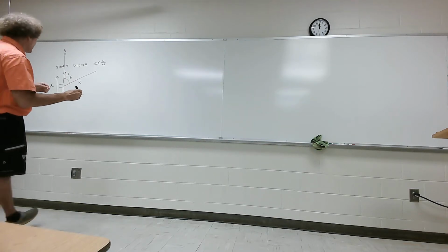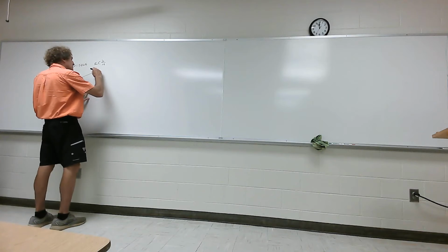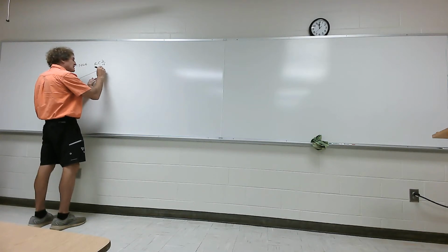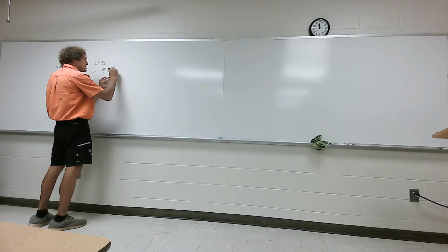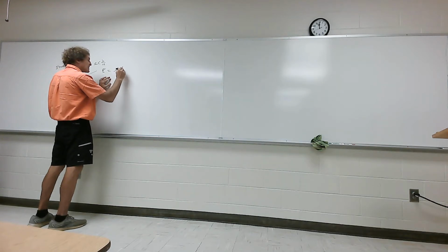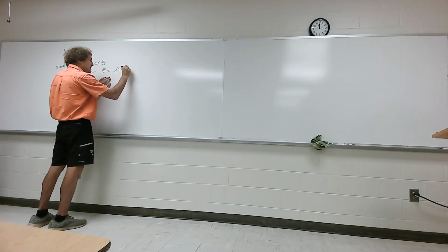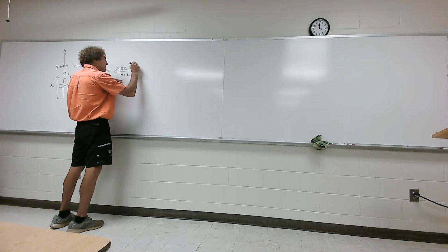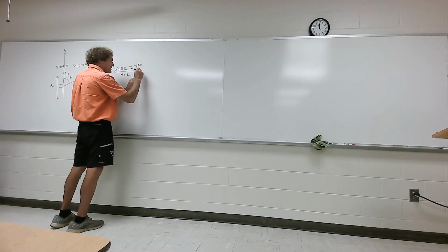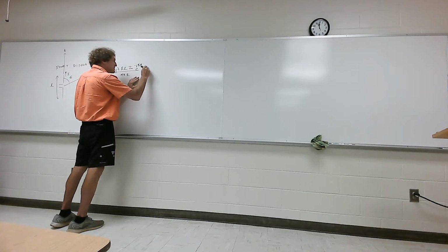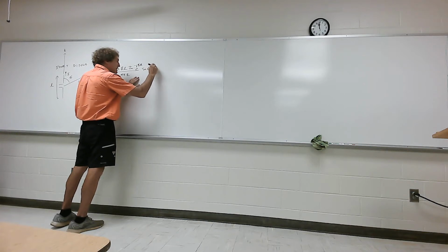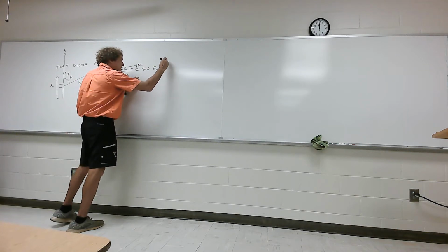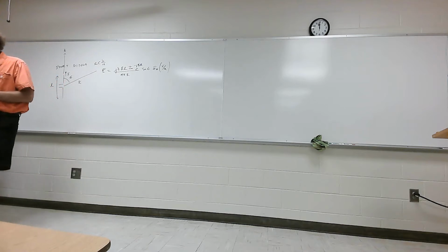And from that, if you're out a distance R away, you're going to get an electric field that's equal to j eta beta times L times I naught, whatever the magnitude of the current is, over 4 pi R, times e to the minus j beta R, and then it will have the sine of theta. And this will be in the a theta direction. This will be in volts per meter.